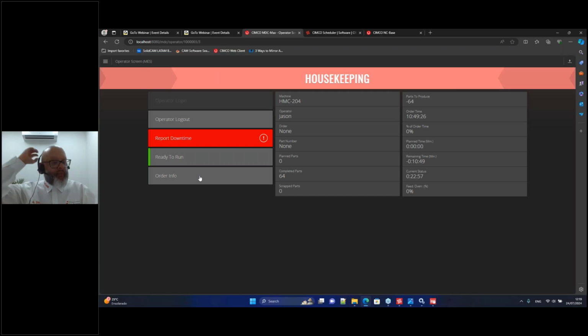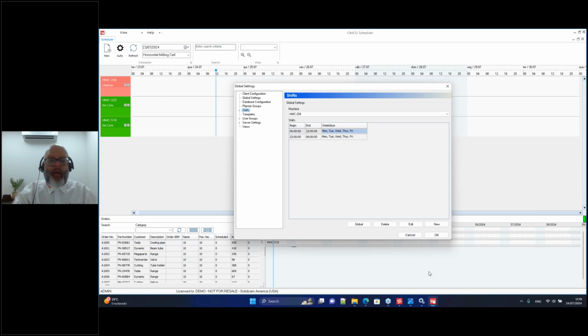So every time, for example, that the operator completes a part, my scheduler will say, hey, you need to finish 10 out of 242 parts. So it starts to count that. You can electronically capture the signal of the M30 on the machine. So every time M30 occurs on the machine, you increment the counter on the scheduler and say, I completed another part. So you can remotely see everything that is happening, including the number of parts produced and everything.